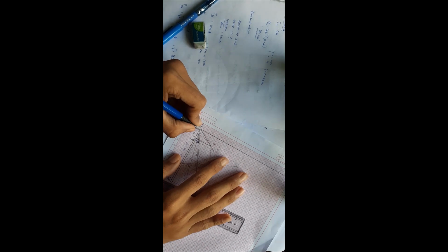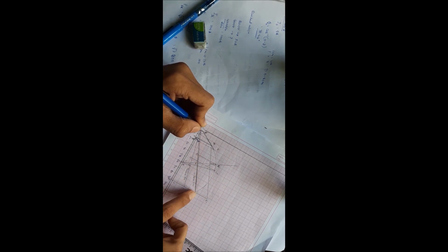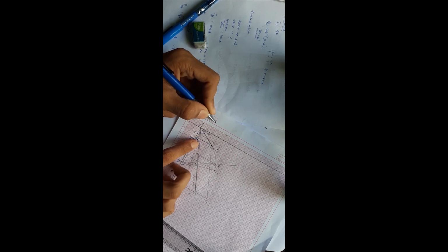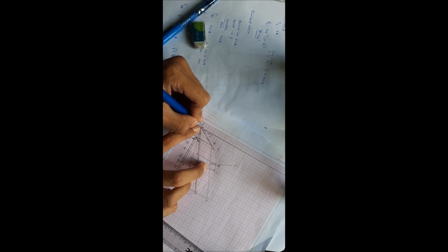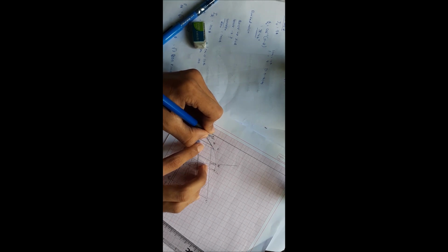Here the angle from our y-axis to the O dash is phi O, and the angle from our y-axis up to our A line, that is output, the blocked rotor current line, is phi SC, and the angle from our voltage axis to the line PO, whatever we did, is our phi.